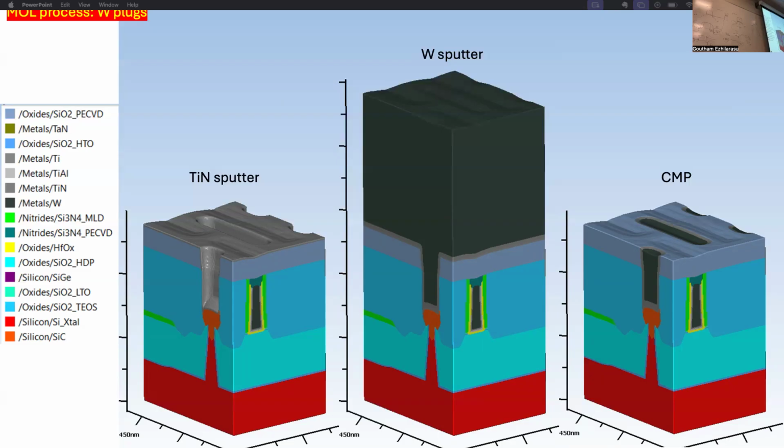You also remove a nitride, high nitride. No, titanium nitride is not a polish stop. Titanium nitride is just a barrier. You remove it, right? Yeah, you remove it. That's what I'm saying. Where did I remove it? After your CMP. Oh, but that's timed. It's not stopping on the oxide. You're polishing over it till it goes away. Oh, I see. You understand what I'm saying?